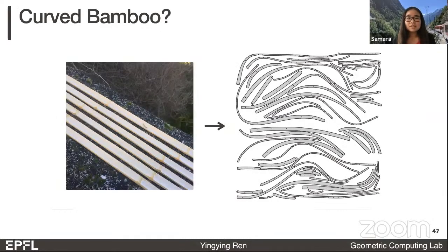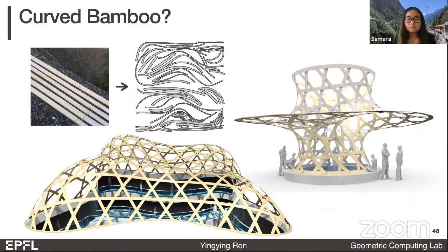Lastly, I want to discuss the main limitation of using curved ribbons. So far, we haven't been able to fabricate curved ribbons using natural materials. The fiber direction in bamboo, for example, prevents us from directly laser cutting a curved ribbon out of it. Even when we use paper, plastic, or metal sheets to fabricate the ribbons, curved ribbons don't pack as nicely as straight ones. One possible solution for this problem is to apply a sparsity regularization term on the curvature variables so that the ribbons can still be curved, but maybe are composed of very similar looking segments. We definitely need to study these problems more when we want to build large-scale structures using curved ribbon weaving.